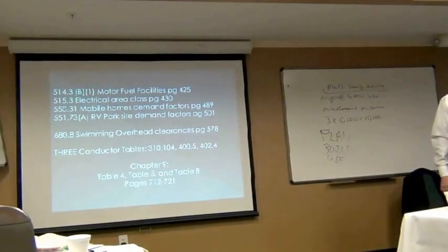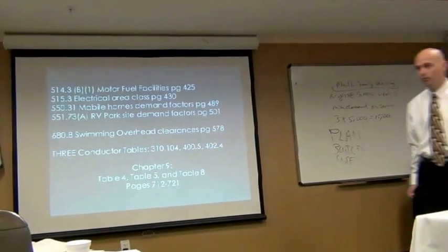So, for example, if I gave you a remote pump located indoor that had a 3 feet above floor level, what would that area be classified at? And you'll see that there's a 2 and a 2 on both columns. I'm on page 426. On the left-hand side under remote pump, indoor, and actually the entire space within any pit would be a 2 and 2. So that's a division 2, zone 2.